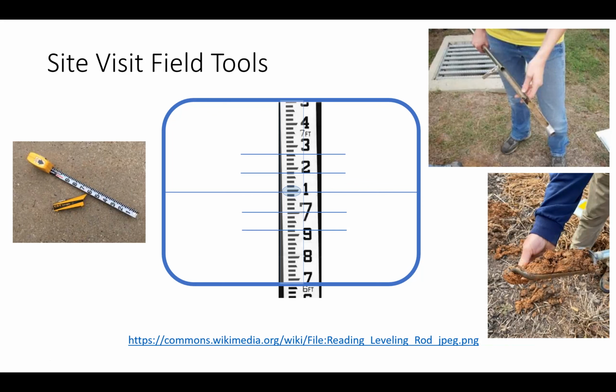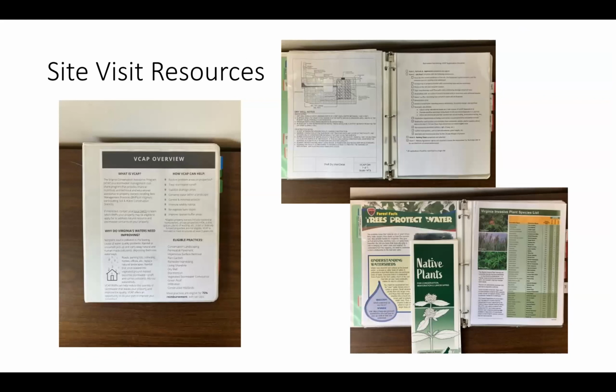So if you're thinking about, say, a rain garden that has to be kind of flat and fill up like a bathtub, if the slope is too steep, that's going to be a lot of grading from the low point to the high point. So this is how you sight through the pocket rod. Some of you do ag work, probably very familiar with this, and others less so. But relative elevations, that's something I'm always interested in terms of thinking about the applicable practice.